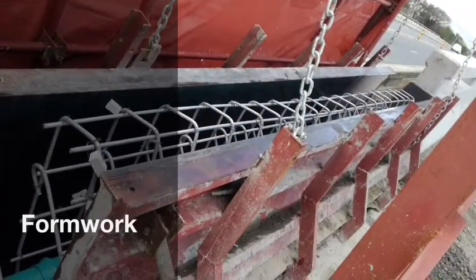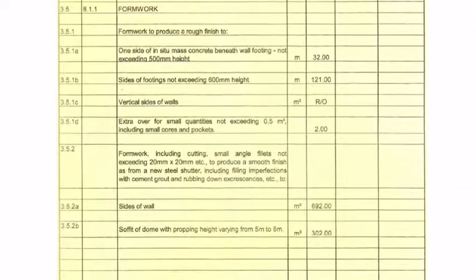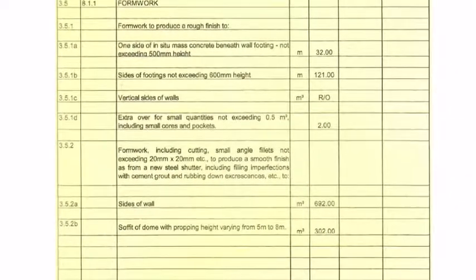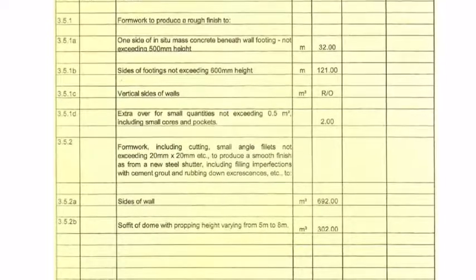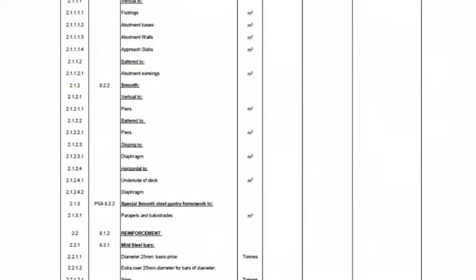For the formwork section of the bill, narrow width and recess were measured in linear meter as required in the SANS 1200G. However, items other than those previously mentioned were measured in meter cube instead of meter square. We deduced that it was a typing error by looking at the quantities.